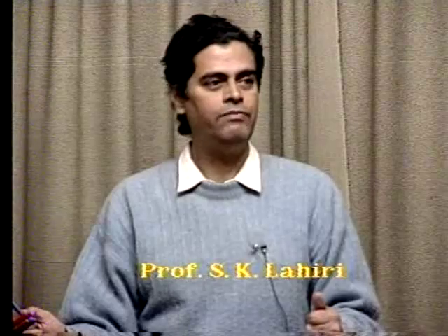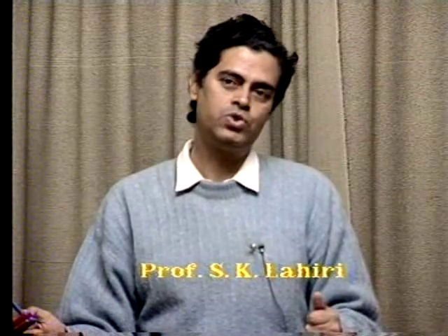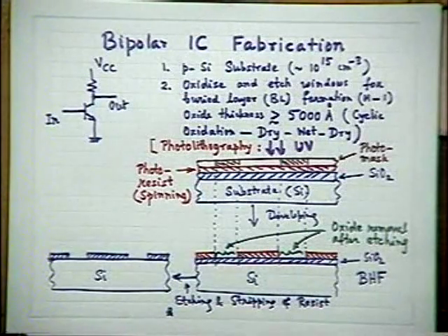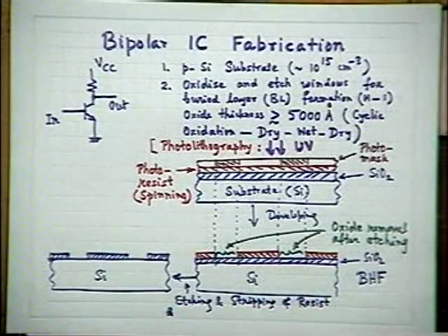It is exposed to atomic oxygen, which is available in plenty, if you mix H2O2 with concentrated sulfuric acid, freshly prepared, then nascent oxygen is created. This nascent or atomic oxygen is highly reactive, and polymer is nothing but a carbon hydrogen oxygen compound. This is readily oxidized by the nascent oxygen and gets converted into carbon dioxide and water vapor, which is removed. It's a very simple technique.